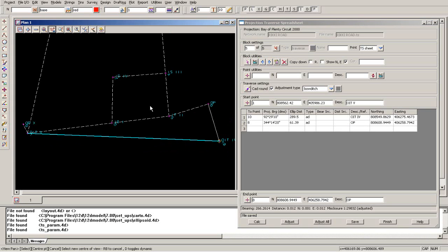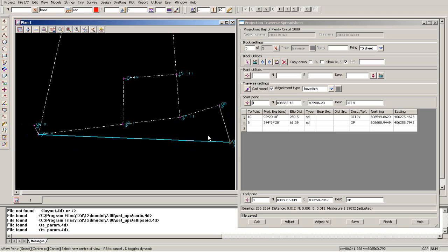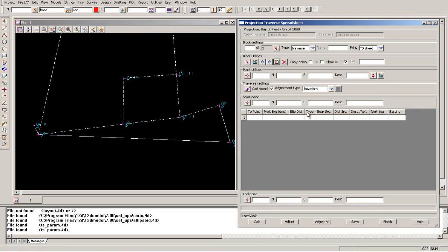Now what I'm going to do is, as I said, we wanted to put the first peg 55 meters from the old peg, and then 100 meters for our lot. So we're going to come down there and check onto that boundary, where these measurements are going to be made. Remember, we've got the total distance there of 208.90, so we're going to close that one out, so that will be a traverse.